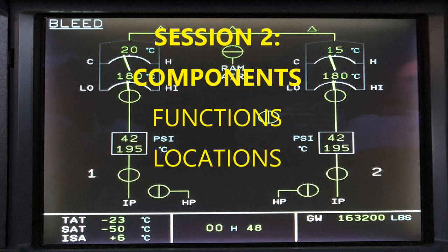It limits it to roughly 36 psig. Then it closes fully pneumatically when the upstream static pressure reaches 120 psig, give or take. So just so you know the triggers, the high pressure bleed valve limits the downstream static pressure to 36 psi, and it closes fully pneumatically when that pressure reaches 120.